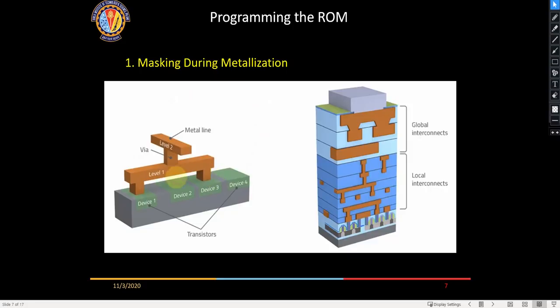If we use a single metal for interconnection of all these areas, it will require a lot of space, because you can't run lines very close to each other; they have to be spaced. The routing itself might take more space than the chip itself. To overcome that problem, what we generally have in VLSI is multi-layer metallization.